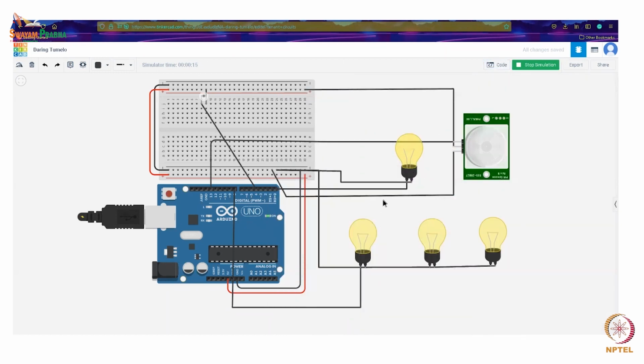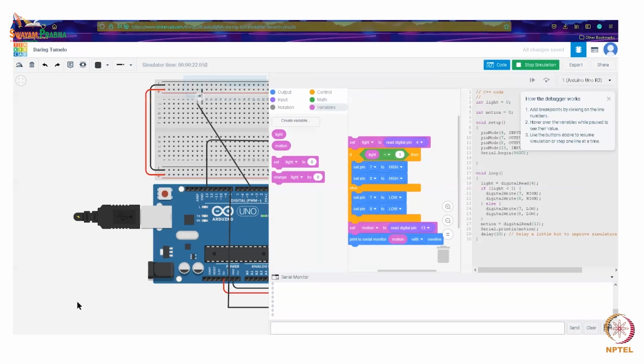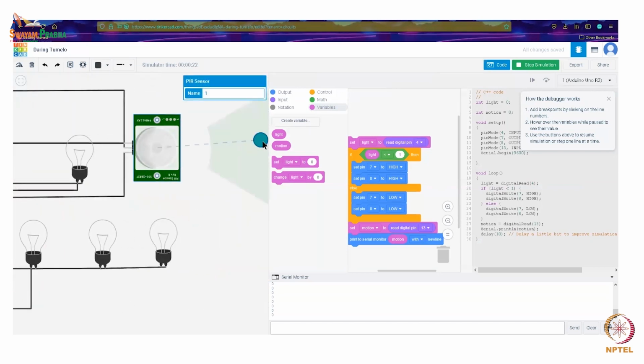So we have the light bulbs on again. So let us make it in the morning. Right now, the PIR has this range. It can basically detect an object, and once it detects an object, it will be printing out to the serial monitor. So let us see that serial monitor. Right now there is no movement, and once we move an object, it goes to high. Once the object passes the lamp, it goes back to zero.